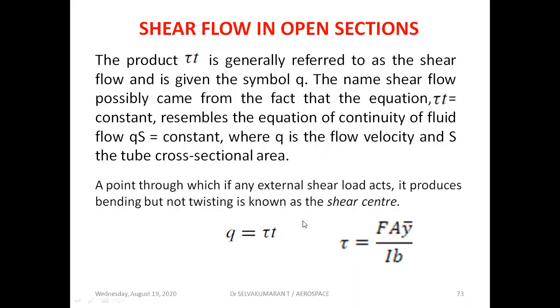Now, in this chapter, we are going to learn how to determine the shear flow values and how to plot all those shear flow values for the given open section. In a future chapter, we are going to see shear flow in closed sections also. The shear flows are generated not only due to shear force but also due to torsion. Due to the application of an external torque, shear flows are also generated.